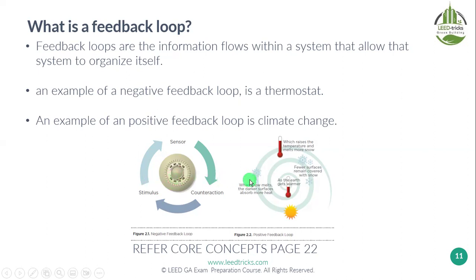Why? Because they told you the starting always takes energy. The starting of the system always consumes energy. So they just say, okay, let's make this air condition just continuously working, the fan, but it will speed up or slow down. Speed up, slow down. So it's always running, but at a low speed or high speed, depending on whether you reach the feedback point, or the temperature you set, or not.